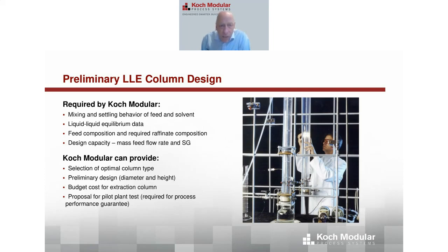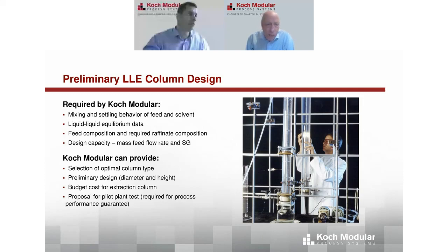We need your feed concentration, required raffinate concentration, and your design capacity. With all of this information, we would select the optimal column that we think would work. We'd come up with a preliminary design for that column, a budget cost for that column, and then we would propose pilot testing to truly guarantee that performance. So with that, I'm going to turn it over to Brendan.